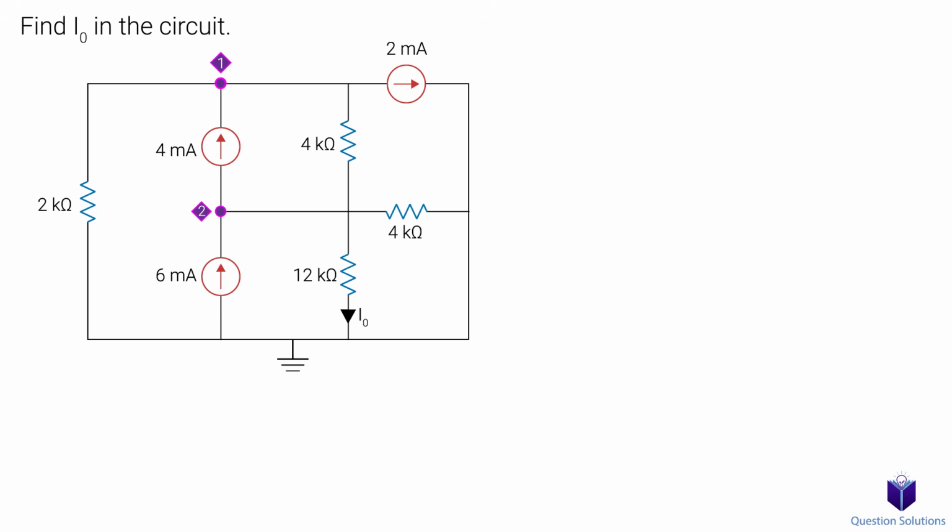Now it might be a bit hard to see how this circuit only has 2 nodes excluding our ground node, but remember, there is nothing between these points, so it's just extra long conductors. Even though we pick singular points to label as our nodes, all of this is node 1 and all of this is node 2. Now we can assume the directions of the current.